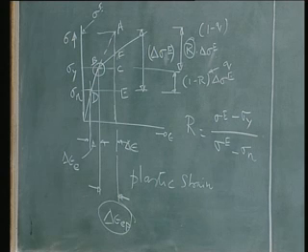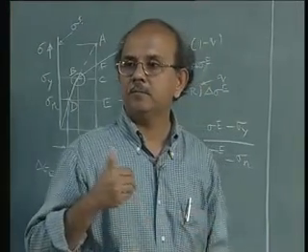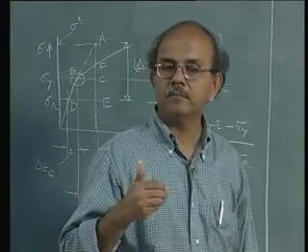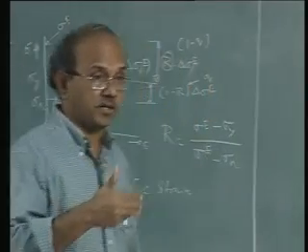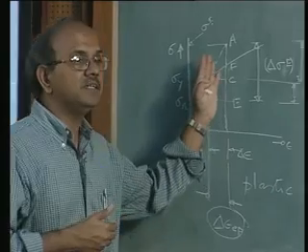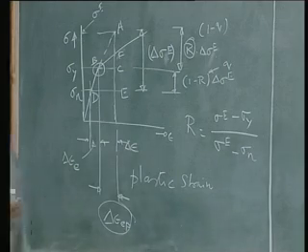Why do we need that? Why do we need to calculate plastic strains? Because I have to update the surface, or in other words, in this case, the yield strength of the material itself. So that makes it important, and let us see how we calculate delta epsilon P, and that is my next step. Let us see how we do that.